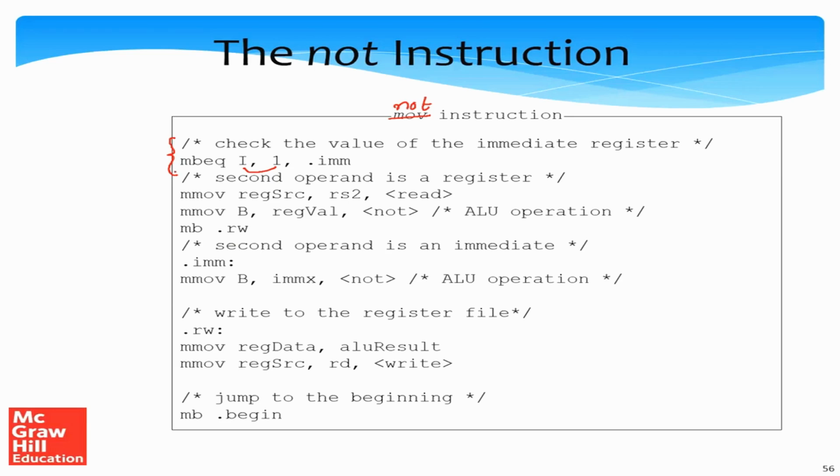So we have always been looking at the first case, the case when the operand is an immediate. So let's take a look at it first. If it's an immediate, we access the IMEX micro register which contains the immediate. We move it to the ALU micro register B. Why? Because recall that the ALU is encapsulated with two micro registers A and B, and even back in chapter 3, we have used B as the source of data for the NOT instruction.